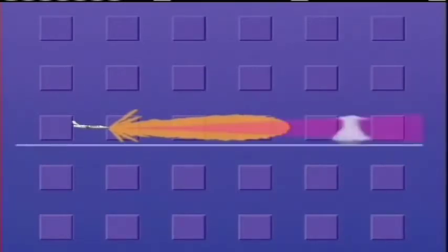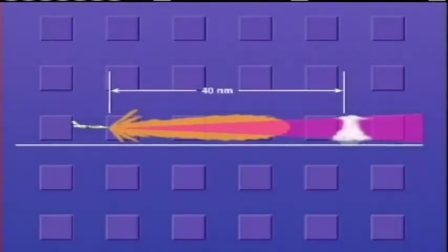Here is a side view of the radar beam characteristic, with a storm depicted at a distance that causes the size of the storm to just fill the 3 dB beam width. This would be the typical situation for a storm at approximately 40 nautical miles with a 12-inch diameter antenna. To enhance your understanding of this tape, it is important to understand and be able to visualize this situation.